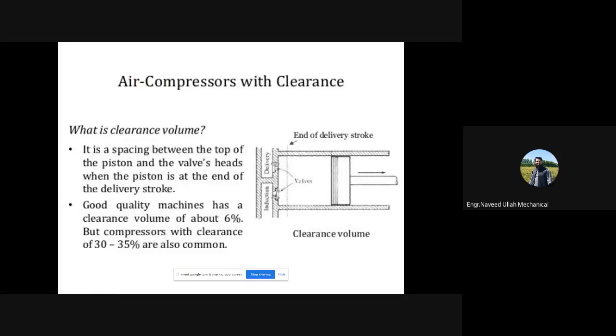Right. So the condition for minimum work की समझ आपको आ गई कि भाई if you want to decrease the work consumed by the compressor, that actually we want, okay, in order to increase the efficiency. There are different possibilities, but some of them are not practically possible. Okay, as far as the indicator diagram or the PV diagram is concerned, we can do alteration over there. We can decrease the length of a line. You can take the line P2 down there, but they are not practical, right?